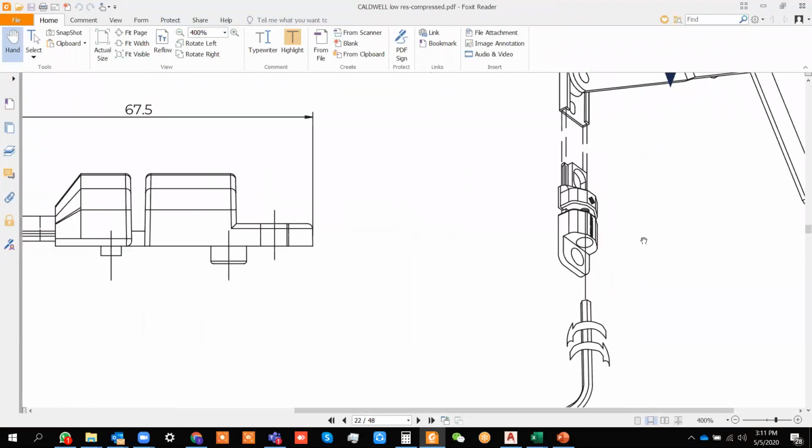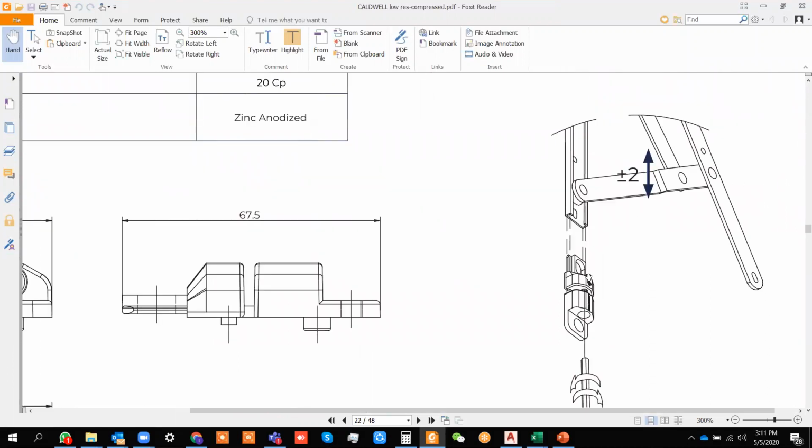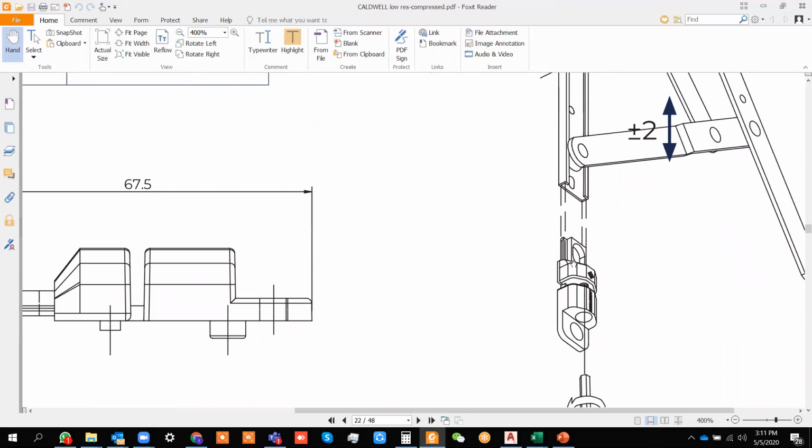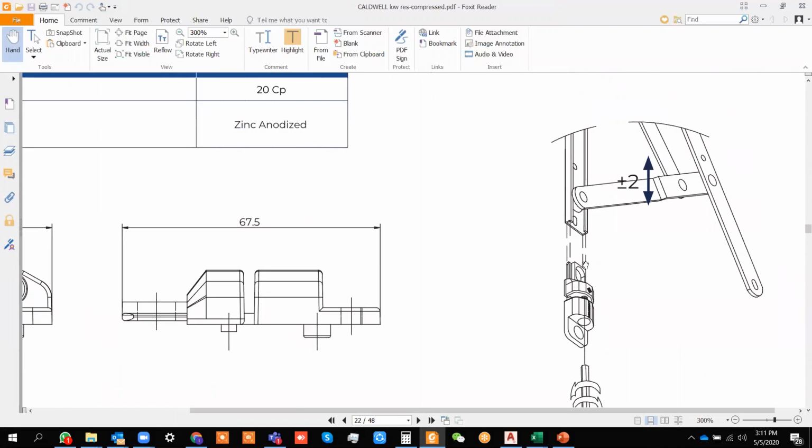The height adjustment block is used from the bottom of the arm like this, and there is an elliptical hole here which coincides with this elliptical hole. As I explained in the very first slide, there are a couple of elliptical or oblong holes, and a couple of round holes. Whenever you fix this, you have to fix the screw in the oblong holes, which are 2 or 3 in an arm, in the channel, as well as in the fourth arm, or the arm which is going to be fixed in the sash. Channel is always fixed in the outer frame, and the fourth arm is always fixed in the sash frame.